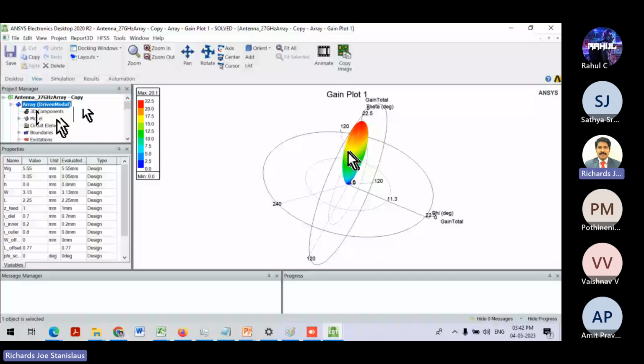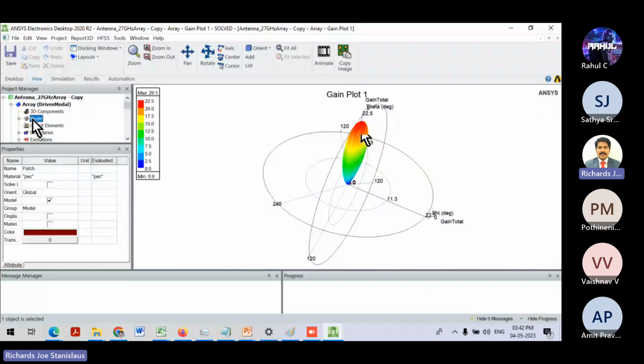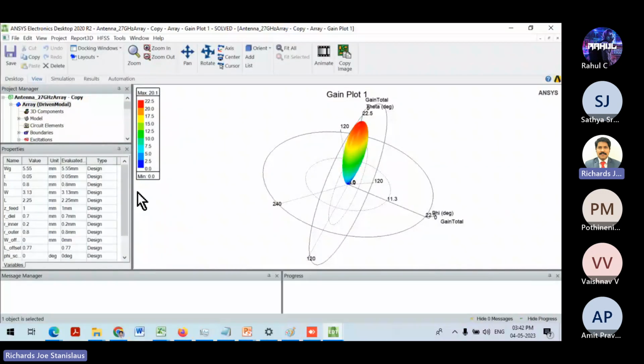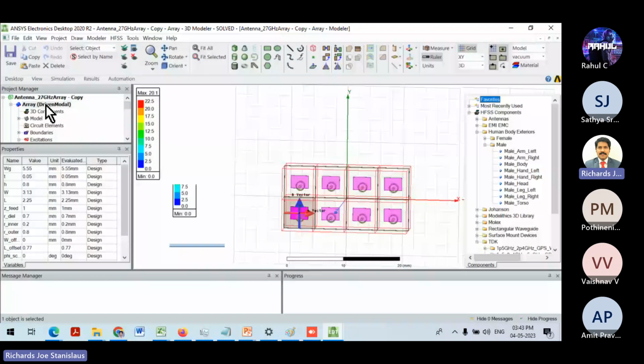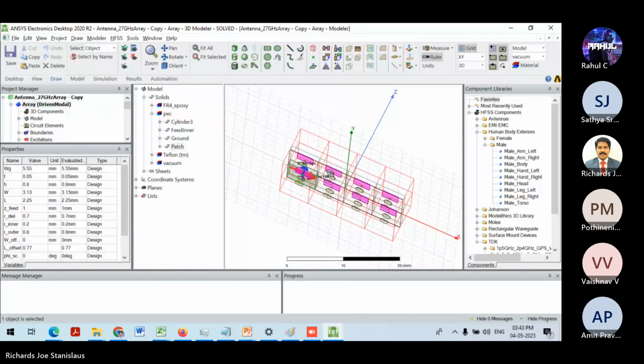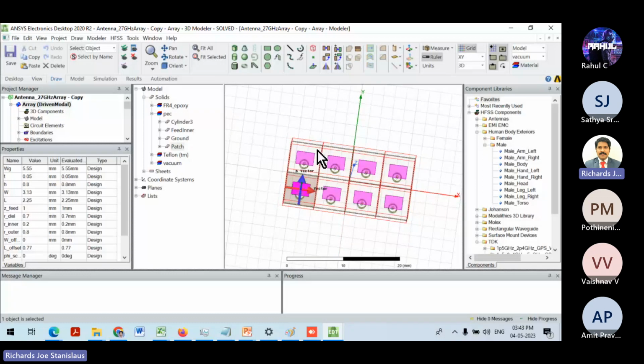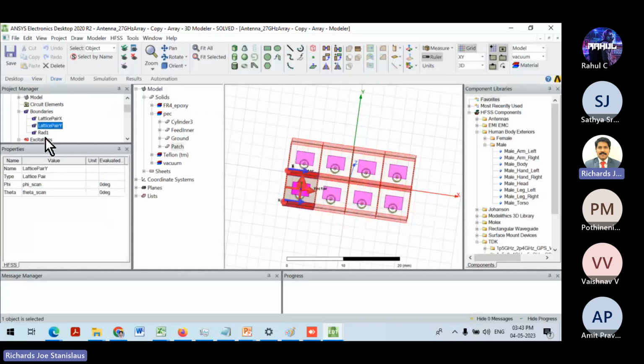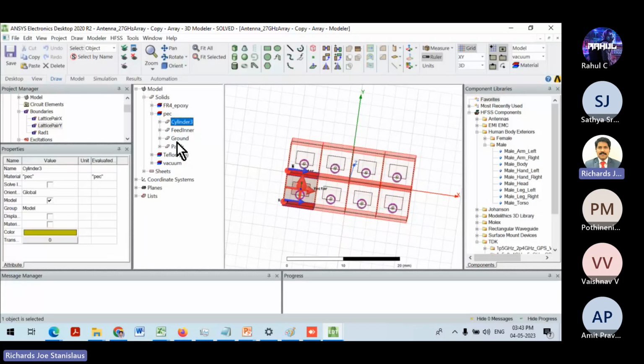Right? If you have very good hard disk space and RAM is limited, I repeat, if you have very good hard disk space and RAM is limited, then you simulate without this approach. What I did was basically the finite array domain decomposition method, wherein we take one antenna and replicate it using the boundary conditions. Without boundary conditions, you are copying and pasting all the elements again and again after some spacing, in that case,